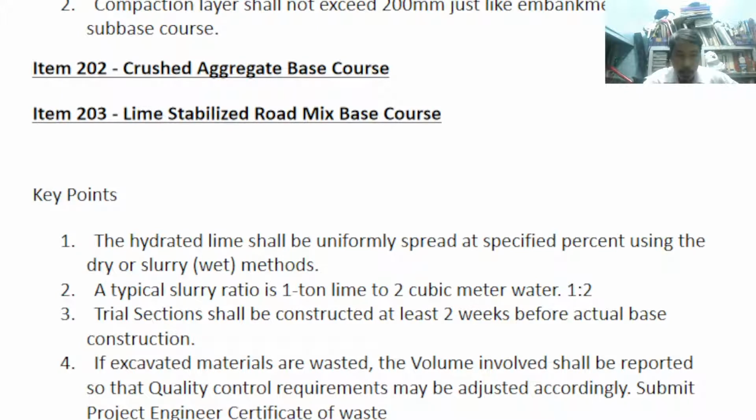Number 1, hydrated lime shall be uniformly spread at the specified percent using the dry or slurry method. Hydrated lime, that is equivalent to cement, shall be uniformly spread using the dry method or wet slurry method.